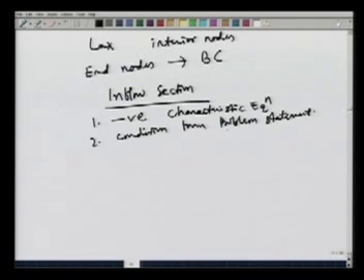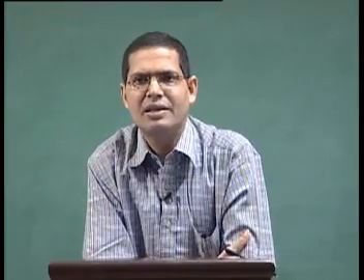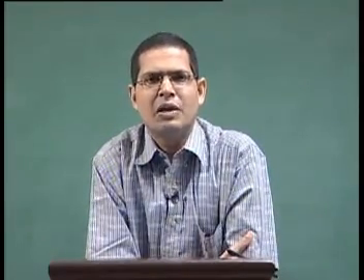So when we say from the problem statement, for example, if this is the channel and you have been provided with the inflow hydrograph, then this is your problem statement. Okay. So one equation is this, the other equation is this. We have two equations and two unknowns, h and u. So one should be able to find both uniquely for the inflow section.